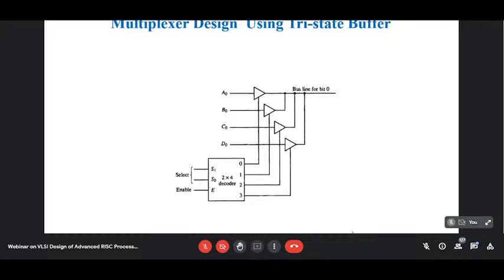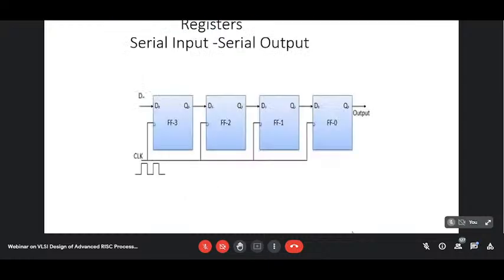So these are MUX circuits. And a tri-state buffer you can easily make with only one transistor. The gate forms the select line, like the enable line, and drain and source can be interchanged as input or output line. So now you understand how these MOS transistors have made things much simpler.